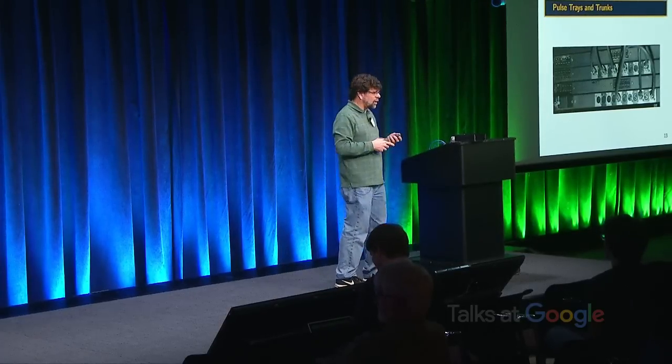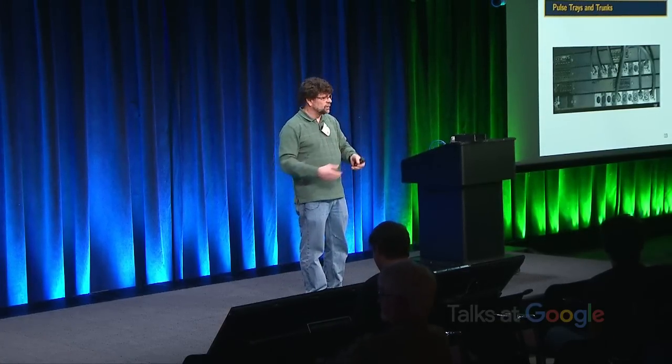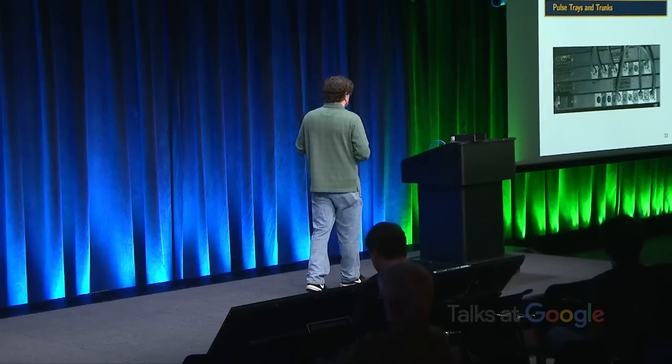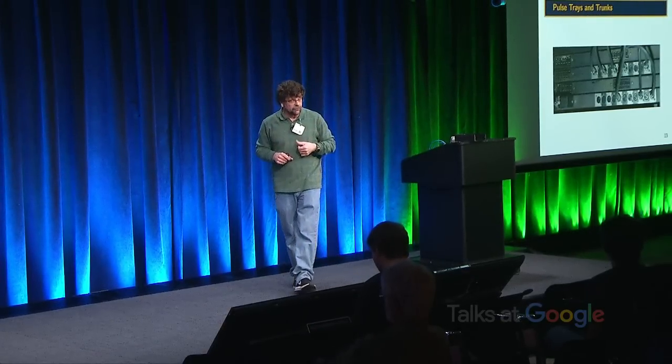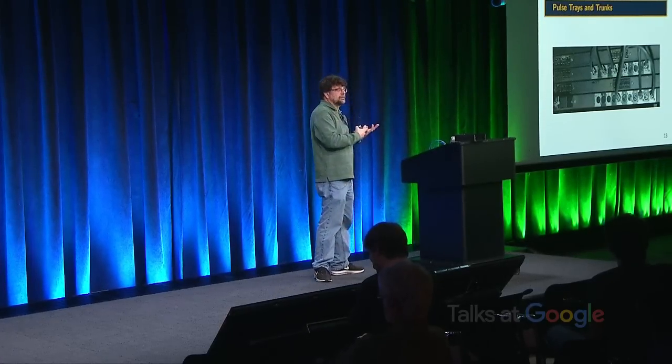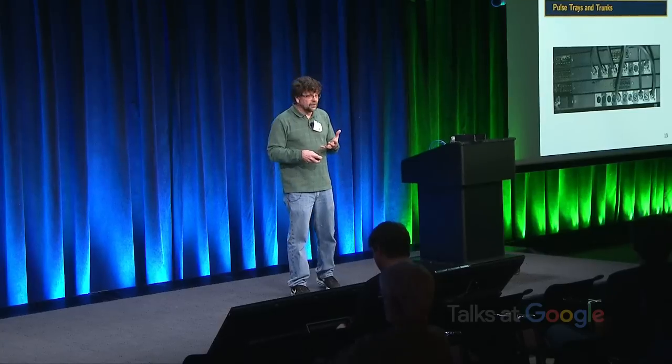Now the interesting thing is these are buses. You can plug lots of different connections into one of these things that ties to all of these other connections. A bunch of them might be transmitters, and you basically get sort of a wired OR behavior. They might be receivers, in which case they're just getting whatever one of the transmitters is doing. So the fact that these configurations aren't fixed, that the programmer can choose whatever they want for the configuration, means I've got to have a fairly general mechanism in the simulator to allow you to sort of connect as many transmitters and receivers as you want to one of these buses.